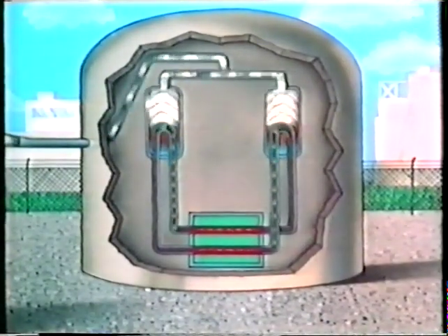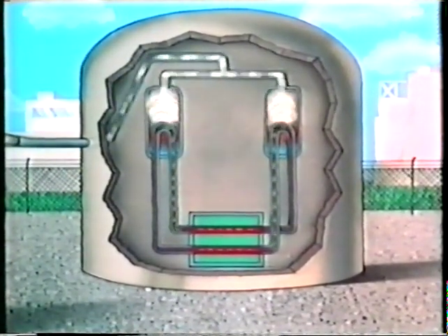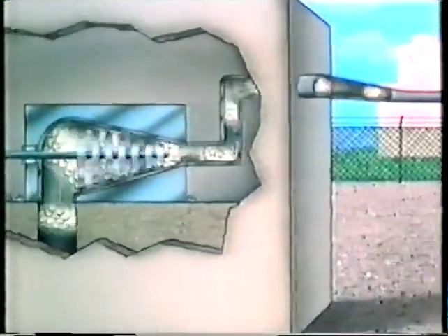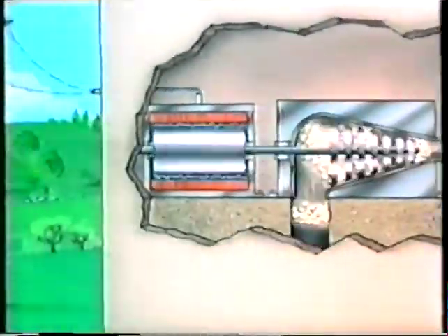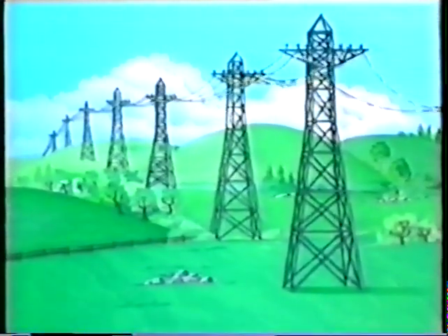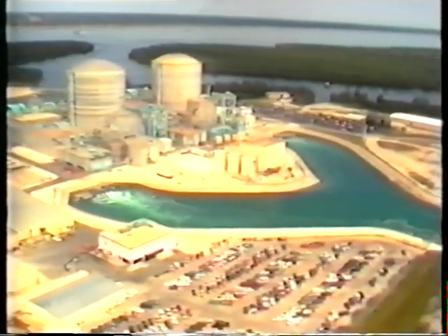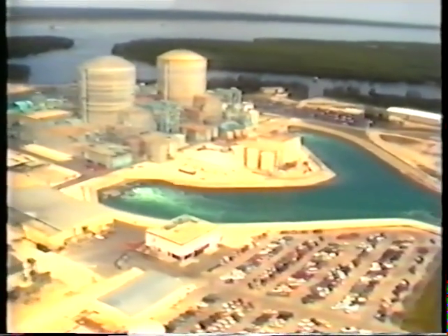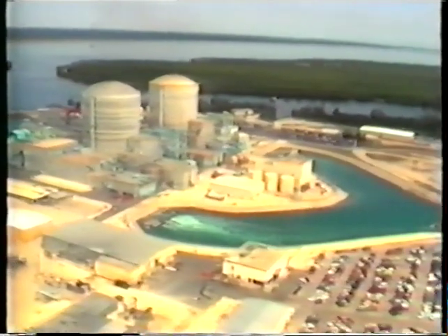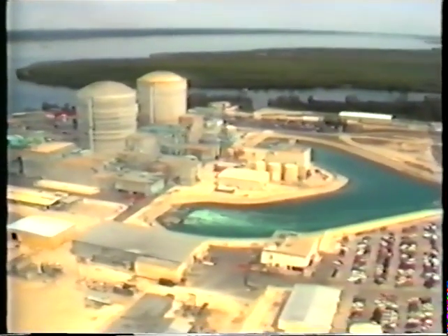A nuclear plant has similarities to a normal coal or oil-fired plant. The fission provides the heat to boil the water, and then steam drives turbines and generates electricity. To generate power, it is necessary to have a temperature difference. Just as important as a hot side is a cold side. So all power stations using steam are sited near a source of cooling water.